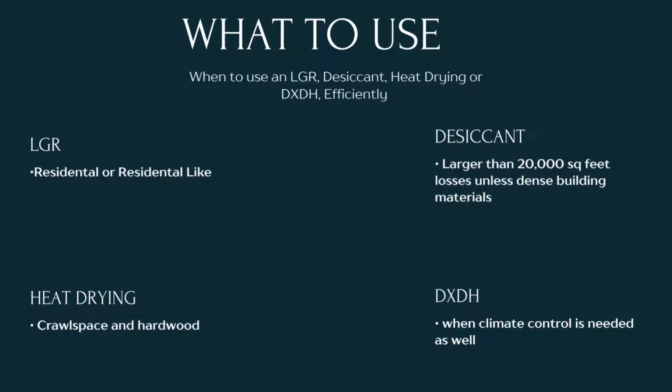But heat drying is really good for crawl spaces. It's really good for hardwood. It's good for plaster. You'll hear some critics out there that'll say if you dry hardwood too hot and too quick, you'll make it crack. I would encourage those critics to Google how they kiln dry hardwood before they put it into the house, and then let them rethink their position.